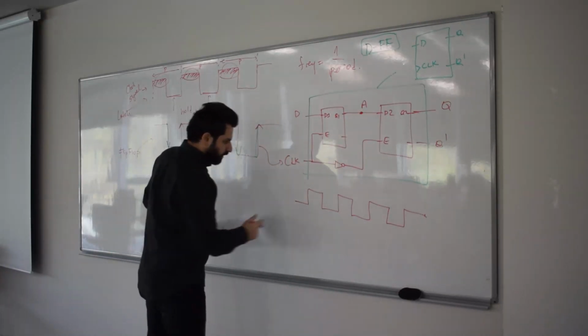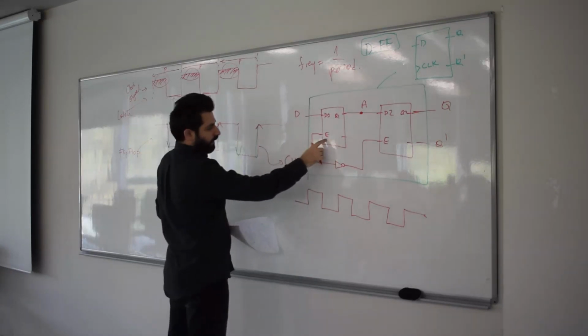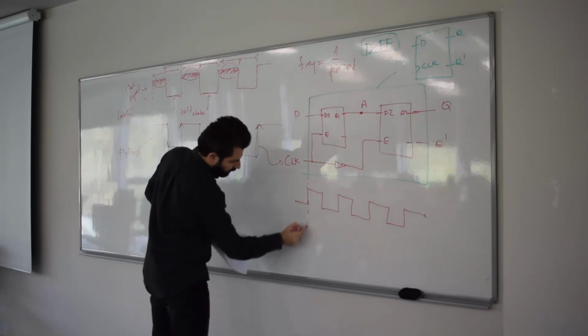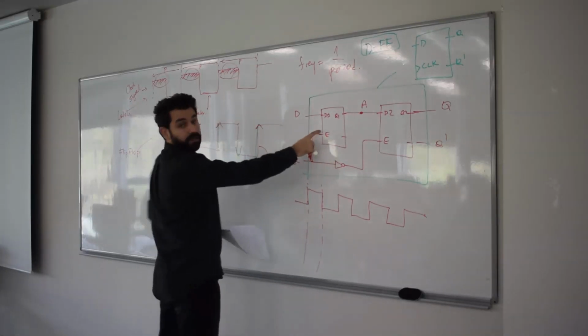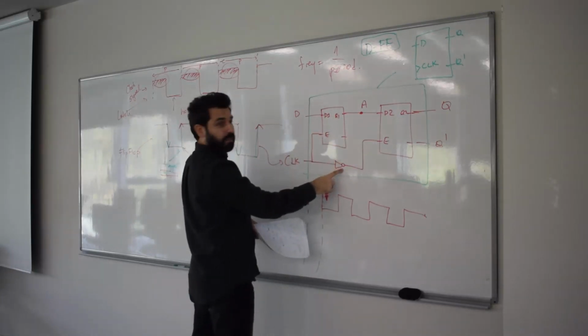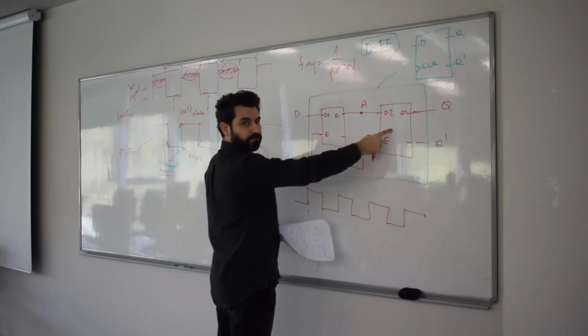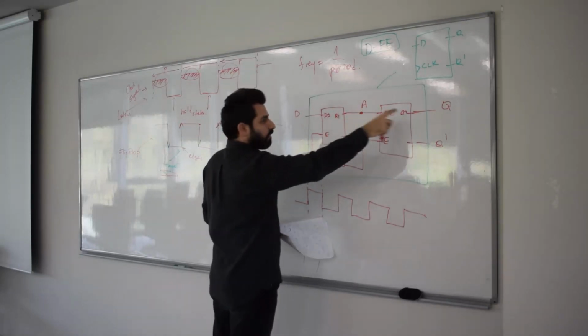All right, now, whenever you have a clock signal 1, okay, I'm talking about this particular time interval, right? If clock signal is 1 here, it is 0 here, right? Because of this NOT gate. So what is that 0 doing here? It's holding it, right? Whatever A is, it's going to be A here.